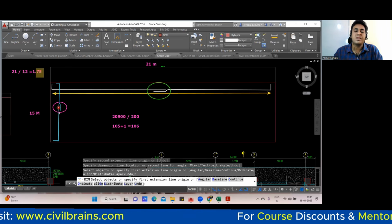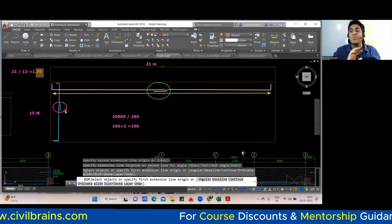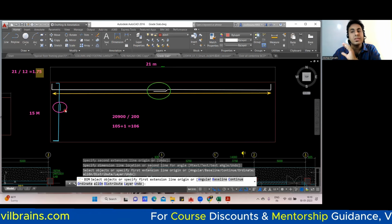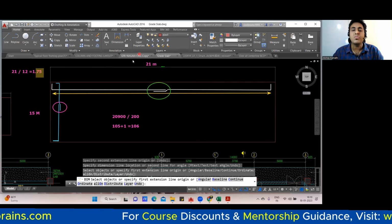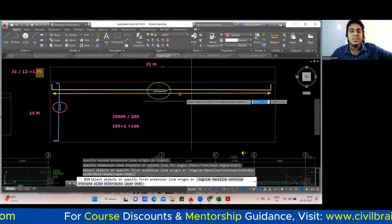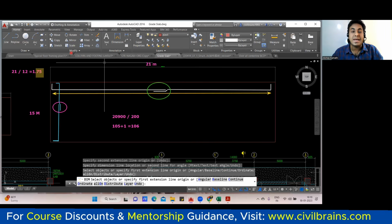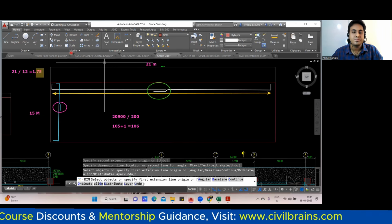And then let us say it's a 16 diameter bar only. Multiply by the unit weight of that, you'll find the BBS. Got it, no? So this is the only difference which will come in the raft foundation. Rest all things are very simple. Only the lap portion you need to understand. But again, there's one more catch in this. What is the catch? I'll tell you.